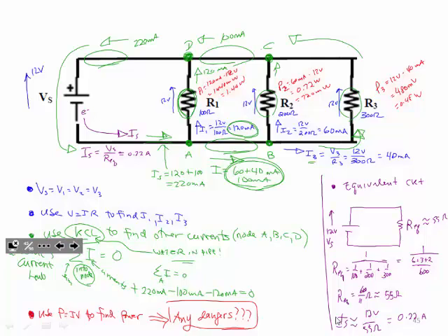All right. And we're going to set my ammeter. Now this should have 0.22 amps, right? 220 milliamps. This scale down here only goes up to 200 milliamps, so I can't use that. So I'm on the 10 amp measuring circuit, at least for this one. I can switch it down to the lower ones to see these three individually if I wanted to.